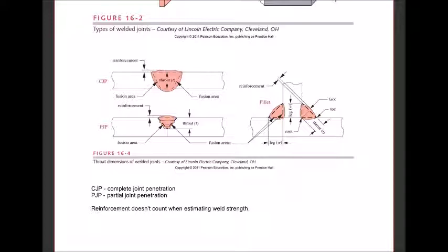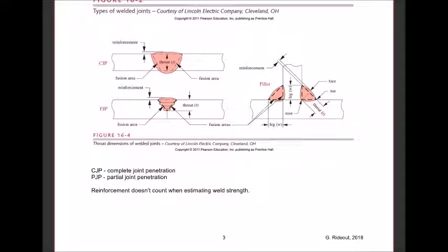When we're estimating weld strength, the big simplification we're going to make, the big assumption, and I'm looking at a fillet weld here with a leg width W, so these are the non-hypotenuse sides of this little right triangle here. So it's a W by W weld. The throat of the weld is this short dimension here. Okay, that throat T is 1 over root 2, 0.707 times the width.